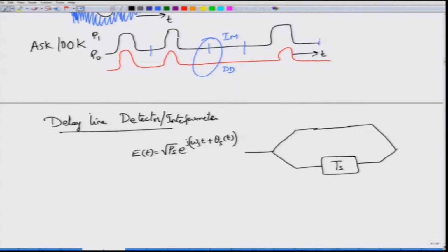So, if I have been able to do that, then what I do is I take the signal, split into two portions, then delay one portion and then combine them at the output stage. Okay. This particular device which is splitting a signal is called a splitter or a combiner, because this is a two-way device. So, you take the signal from the left hand, then it will split the signal into two equal parts. Here we are assuming equal parts. You can actually split them in any ratio you want. You want to split the top part to contain 90% energy, bottom to contain 10% energy, you are welcome to do so. Okay. So, in this case, because we are splitting equally, and this splitting is actually power splitting.